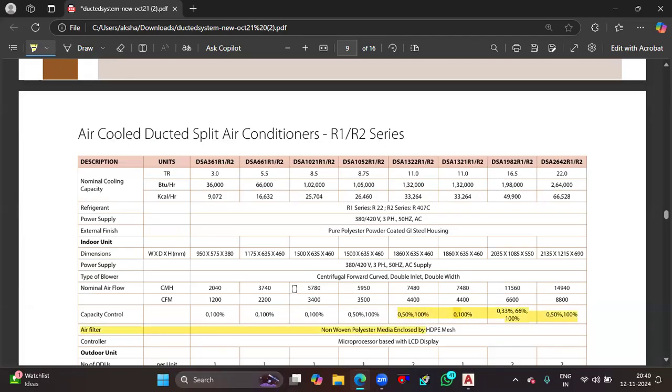Okay, then the thing that we need here is about the choosing of the machine. So 6.210, which means I can't choose 5.5, isn't it? Why? Because it should be less sized. So the only option that I need to go with is the 8.5 ton itself. All right. So 8.5 ton is the actual machine that I will be requiring for the project according to your company aspect. I told you guys, actually, I'm considering this according to Blue Star.